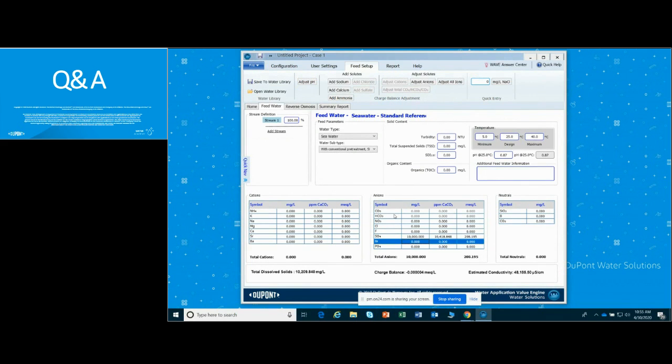Okay, so in this particular case, you can type in 10,000 milligrams per liter of sulfuric acid, and it predicts a pH of 0.87. Obviously, if you put in too much acid, we're going to have trouble at high concentration acids of getting a reasonable pH. But I can get up to 10,000 without a problem. 100,000 is beyond the limits of the program.